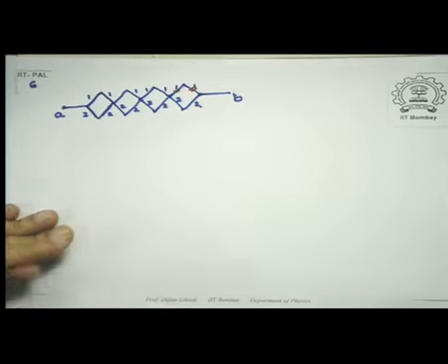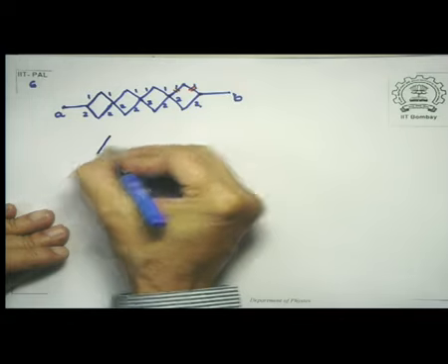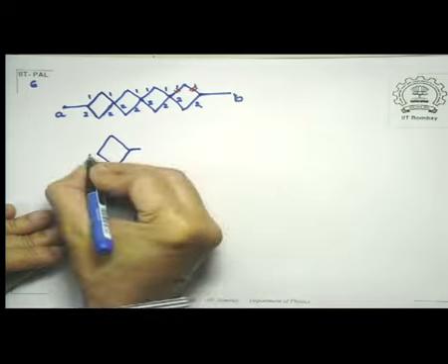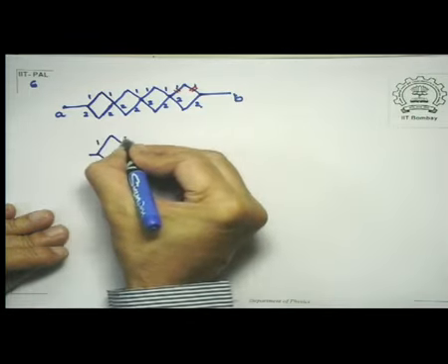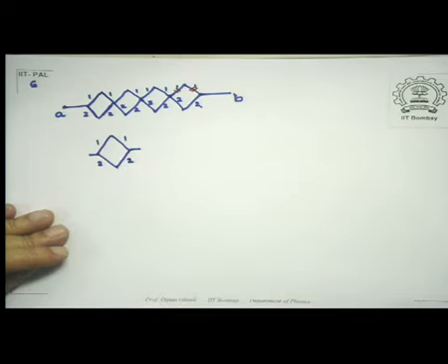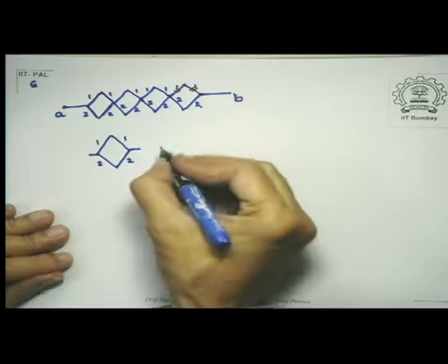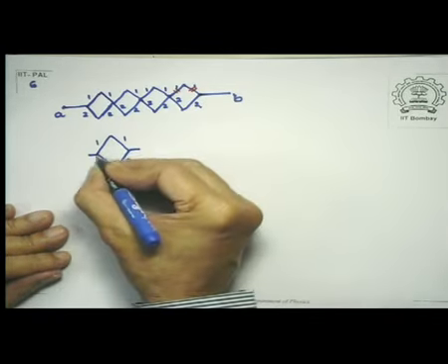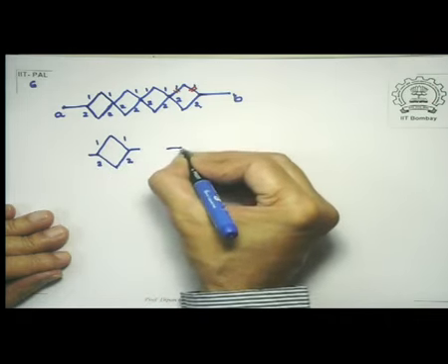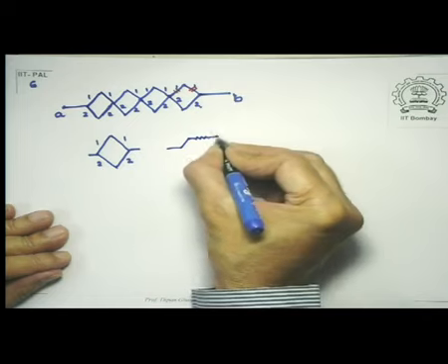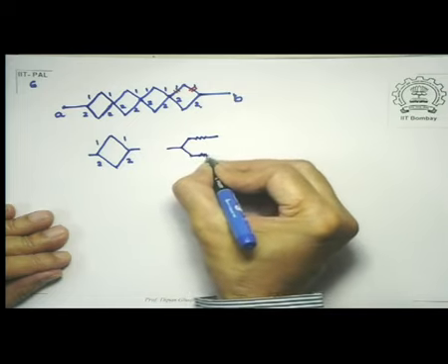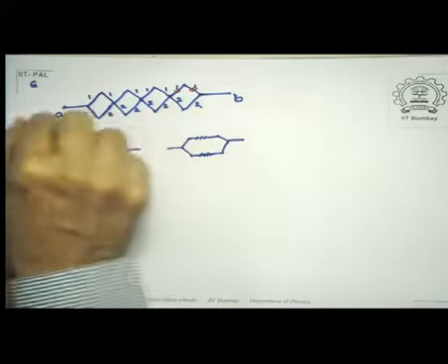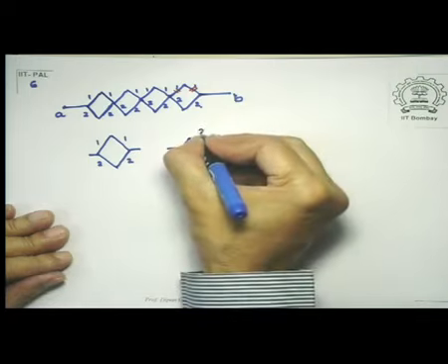So this section that I have got here is connected to the next one. This is 1, this is 1, this is 2, this is 2. So this is the same as a 2 ohm resistance in parallel with a 4 ohm resistance. So I can redraw this circuit like this. Each of these sections will be connected to the next section, and 4 of them will be there. So this is 2 ohms and this is 4 ohms.